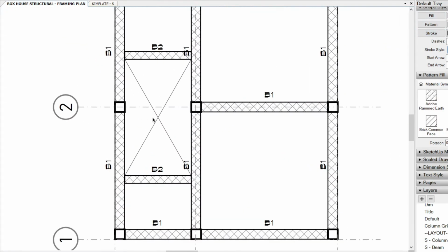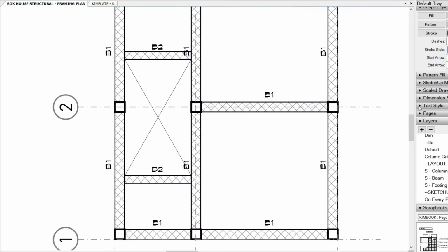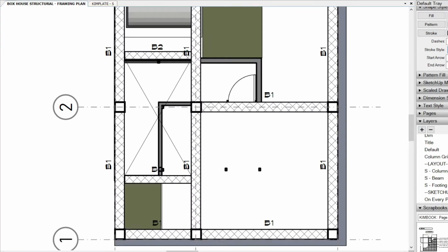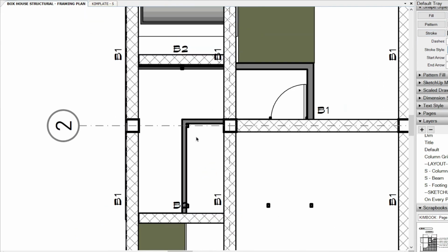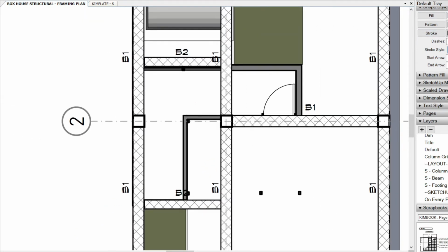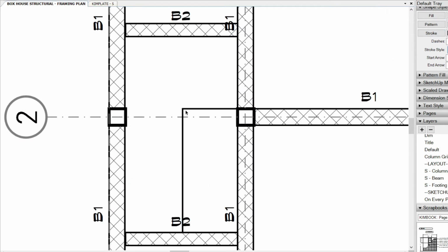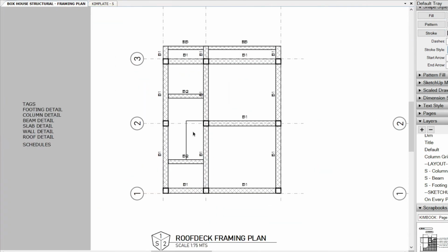I have to check if my stairwell is the same, so I'll turn that on. And I see that this actually has a slab. This is the only hole in the stairwell. So that was wrong. I have to outline that floor slab. Turn off the fill. And when we turn that SketchUp floor off again, you could actually see the outline of the slab.